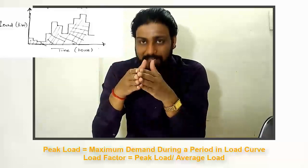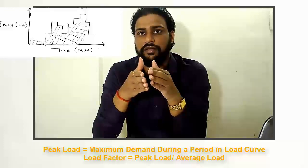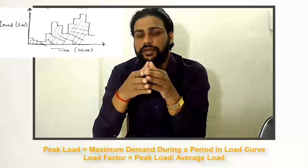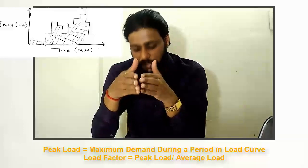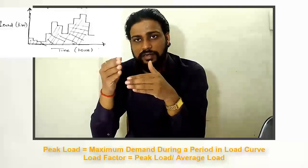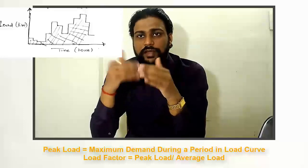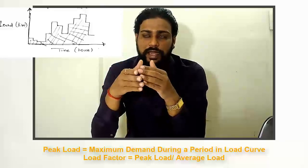And the average load is the area under the curve. So if you have a demand of 1000 at 9 o'clock in the morning, and a demand of 1200 at 10 o'clock, you have a varying graph. If you average that over 24 hours, you will get your average load. It's usually possible that your maximum demand was 1500 and your average load will be close to 1400 or 1300 in the example I am taking. So your load factor will always be less than 1, that is, the average load will be less than the peak load.